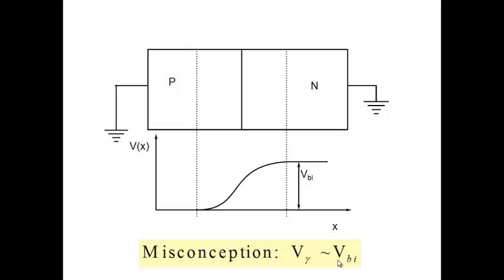The cut-in voltage is, so you're carrying an impression what? You're carrying an impression in your mind that below cut-in voltage, the current is very small. Above cut-in voltage, something happens and current increases rapidly. So you're carrying that impression. Then you know that if I look at a positively charged carrier, it encounters a barrier. A hole encounters a barrier in going towards the N side. And therefore, it must be that once I remove the barrier, then the current really takes off.